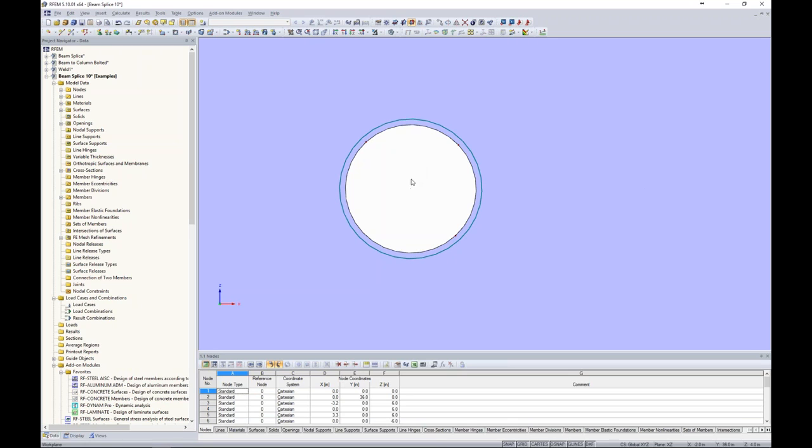Now, those bolt members we'll get into in just a minute, but what they're going to do is to frame into right in the center of these openings. Now, they're 1D member elements, so the question is, how do we connect those 1D member bolts right here in the center to the rest of our plate surface? Well, the answer to that would be small little rigid links.